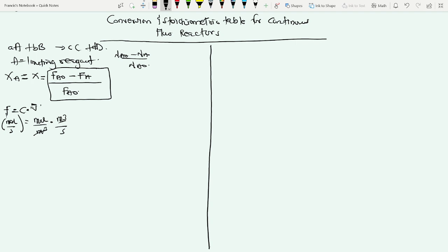And when you are dealing with liquid phase reactions, from our previous video, we were able to establish the fact that liquid phase reactions mostly occur under constant volume. So our v is equal to our v0. So our volumetric flow rate will be equal to our initial volumetric flow rate. So we can substitute that here. So FA0 becomes CA0 times v0, and this is equal to CA0 v. So we can just substitute them here.